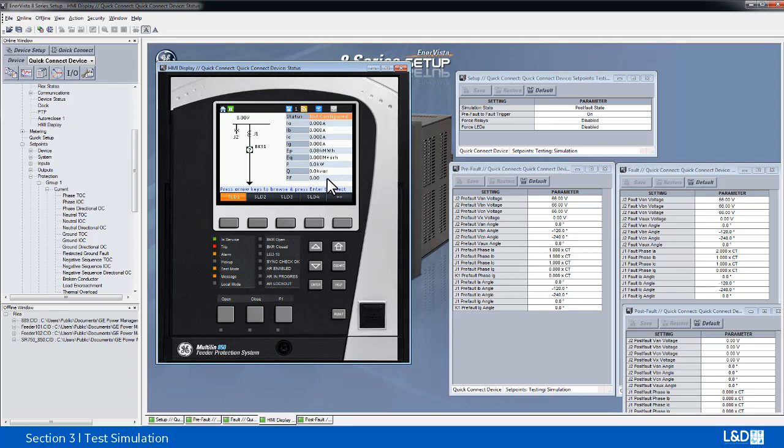And we can see that at the end, the fault current is cut off because we set them in the post-fault. This is similar to the 3-phase test set auto-off function. For some application, we want to keep this current applied without tripping the current.